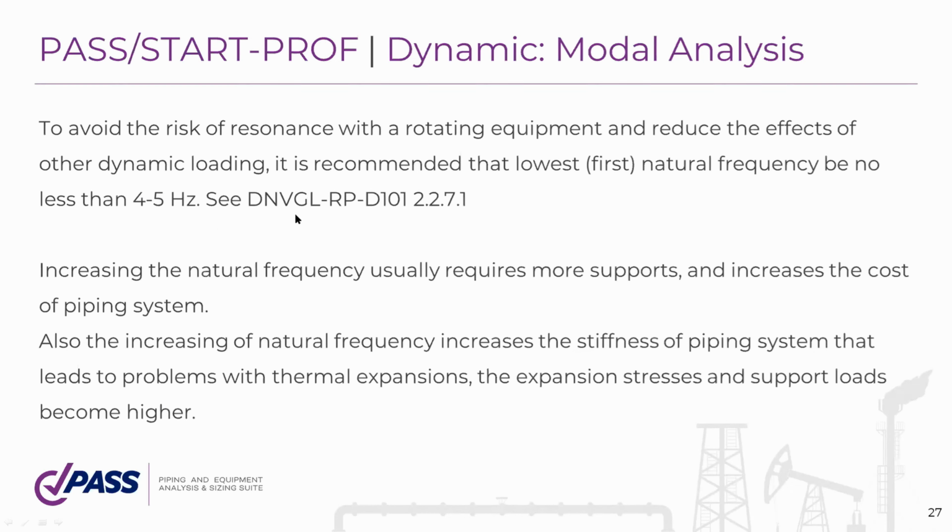If a natural frequency is lower, then the risk of possible problems with vibration due to rotating equipment, slug flow, wind loads, and other dynamic effects will be high. So it's recommended to keep the first natural frequency greater than 4 to 5 Hertz.